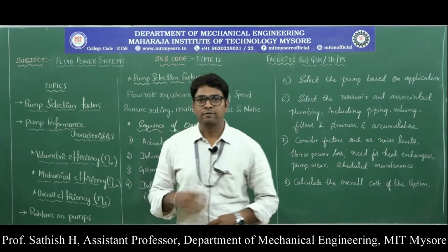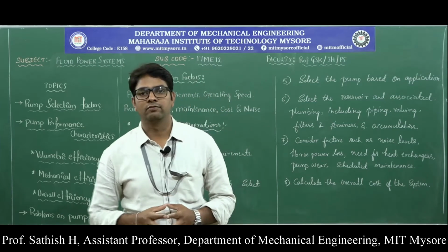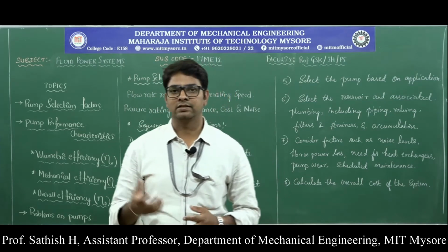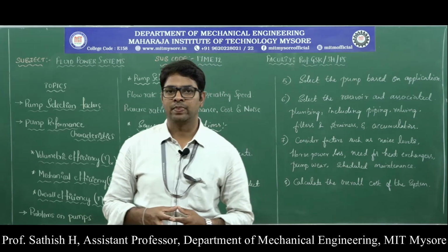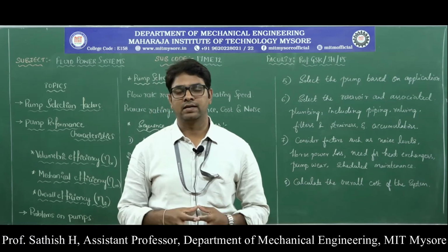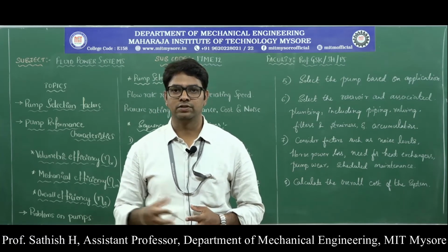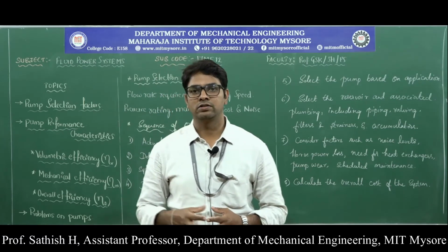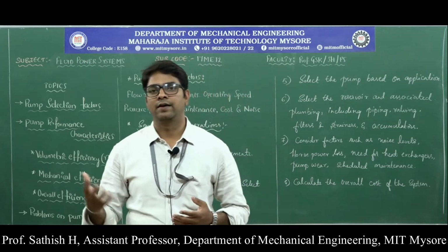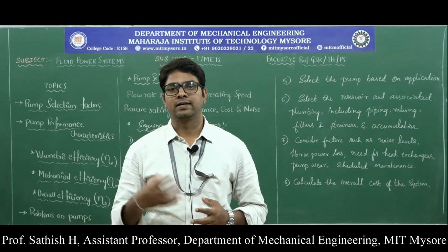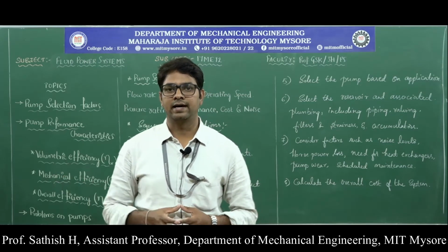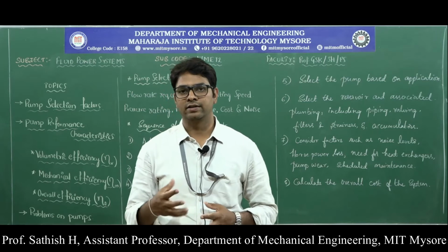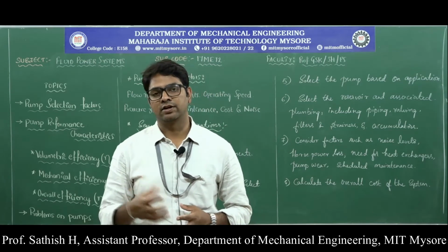We know that in hydraulic systems, or fluid power systems, various components are involved. In order to do a specific application, for example, we have a pump which drives the fluid through the system, and then we have control valves in order to control the pressure, flow rate as well as the direction of the fluid, that is respectively called the pressure control valves, flow control valves, and direction control valves.